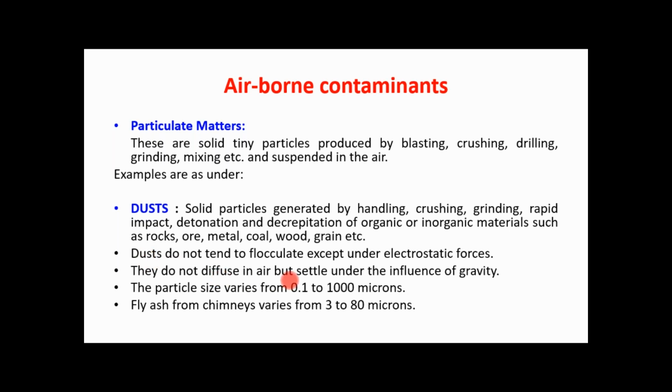They do not diffuse in air but settle under the influence of gravity. So if you use gravitational force or electrostatic forces, that is, cyclone separators, electrostatic separators, Venturi scrubbers or settling chambers, etc., then we can reduce the quantity of dust in the air.